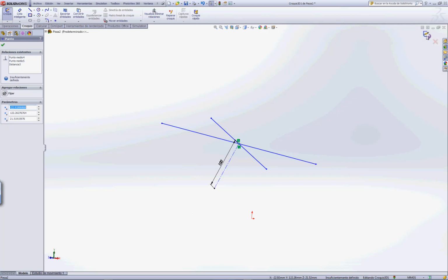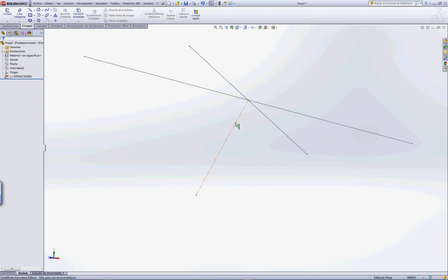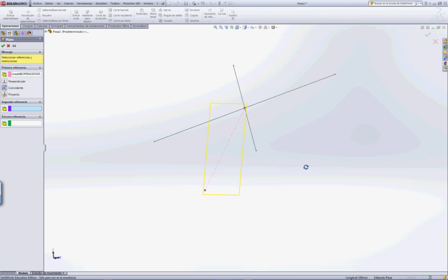In order to visualize both geometries in an easier way, we are going to build now the sphere first, and then we will build the plane. So what we need to do is create a plane containing the radius of the sphere, or one diameter of the sphere, and one circle of the sphere. This auxiliary plane needs to intersect with the center of the sphere. This means that the resultant curve from the intersection of this plane and the sphere is going to be a circle.